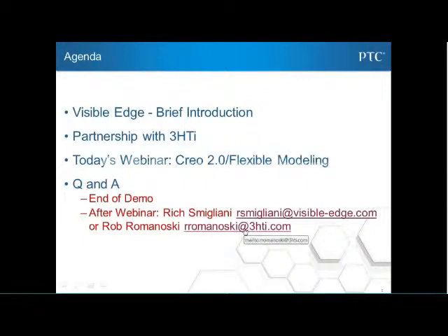Any other questions at all, Greg? Yeah, there's actually one now. Can you reorder features? Yes, you can. You can reorder features just like regular parametric features. The only time you can't reorder them is similar to Pro-E parent-child relationship: you can't reorder a parent to come after the child. But they reorder in the same fashion.